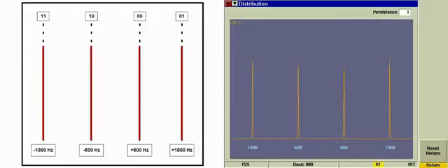Like the constellation display, the distribution plot shows the deviation of each symbol. The horizontal alignment of each peak to the vertical dotted lines corresponds to the alignment of each deviation point to the ideal position. The horizontal width of each point is a function of the RMS deviation error of the signal. However, the amplitude of each peak provides additional information not found in the constellation display. The vertical axis indicates the number of times the signal deviates to each deviation.